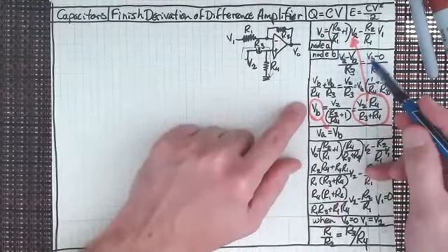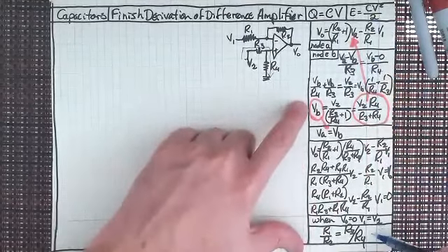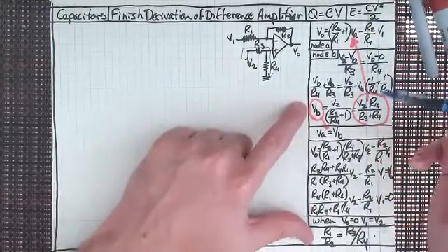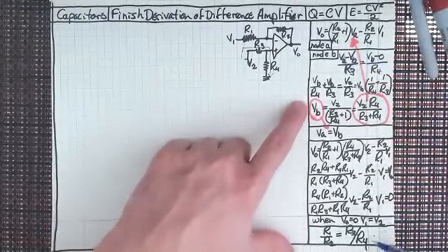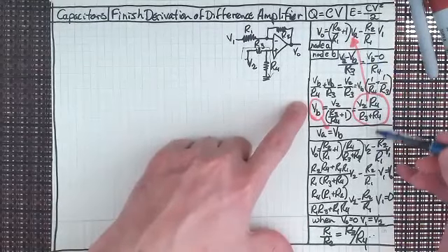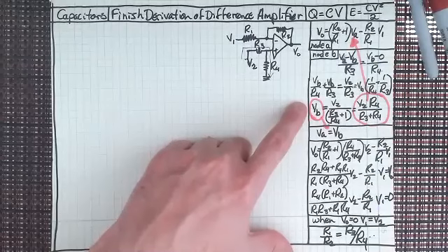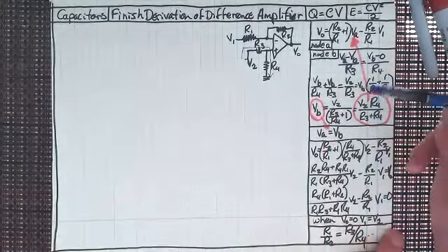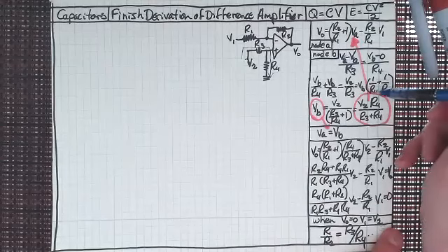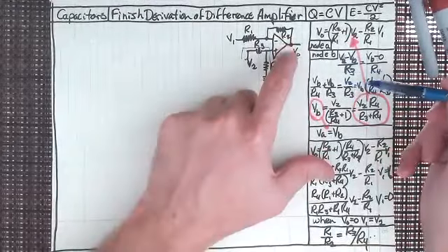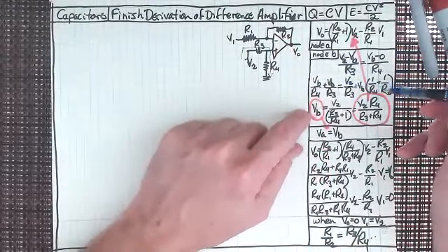And these are all the steps that go from here down to here, right? You can see that basically they went from this point here all the way down to this point here and left out all of these steps in between. And I think it's important to see how they did this. Now, all I'm doing is you can see 1 over R4 plus 1 over R3. If I made both of those R4, wait a second, what am I doing? Yeah, V_B, take that out of there, and I have 1 over R4.